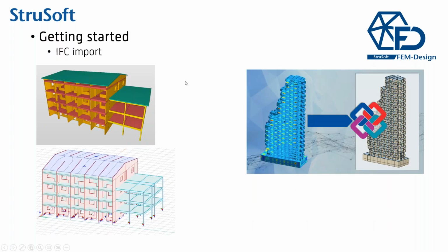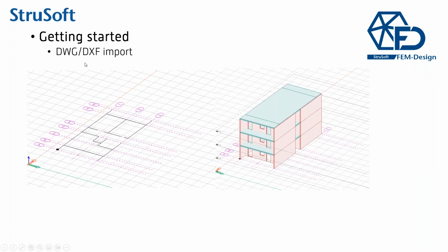And then, how do you get started with FEM-Design? Well, one option is to get started with IFC import. So if you have an IFC model from other programs which you want to use in our software, you can import it. This is an IFC model and this is how it looks in our program. I'm going to show you this and how to fix the IFC model in FEM-Design so it can be used in the best way.